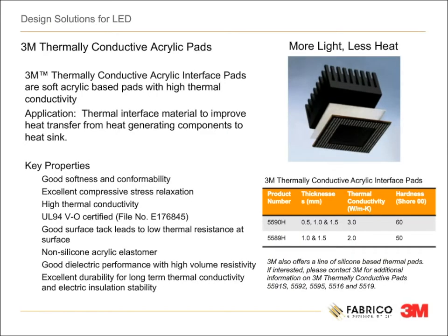5590H is our go-to acrylic gap pad material. It offers 3 watts per meter Kelvin and good conformability at approximately 30% lower cost than silicone pads. The only limitation is the device must run at or under 100 C in service, but can take short-term dwells to 130 C.